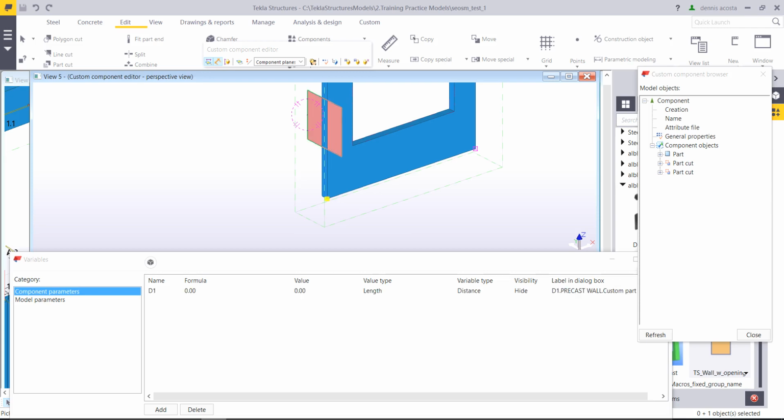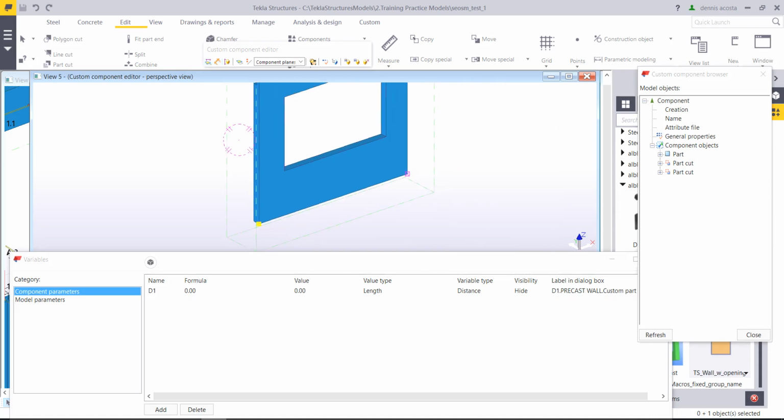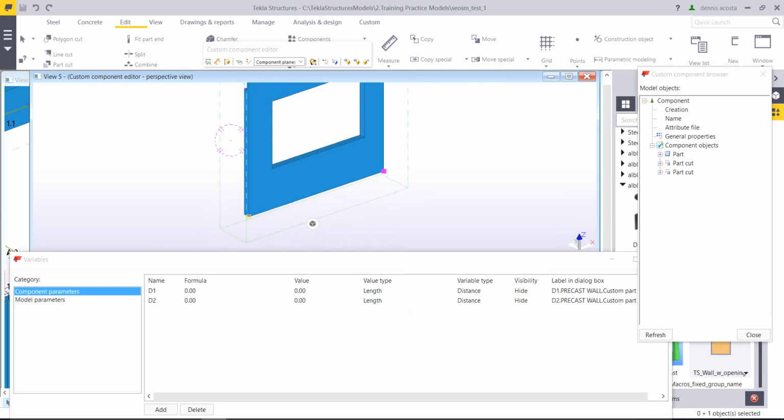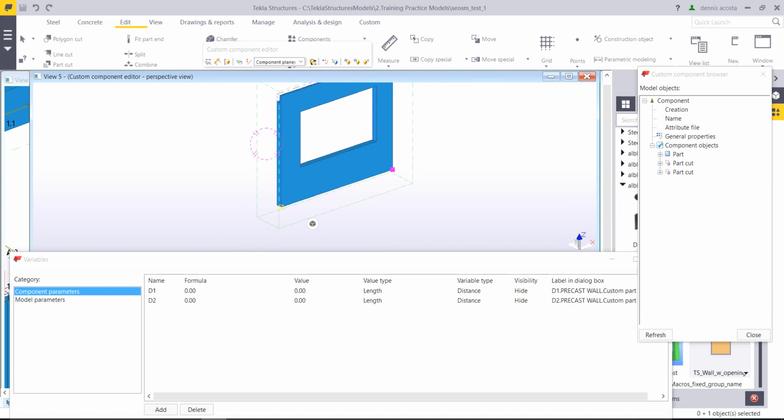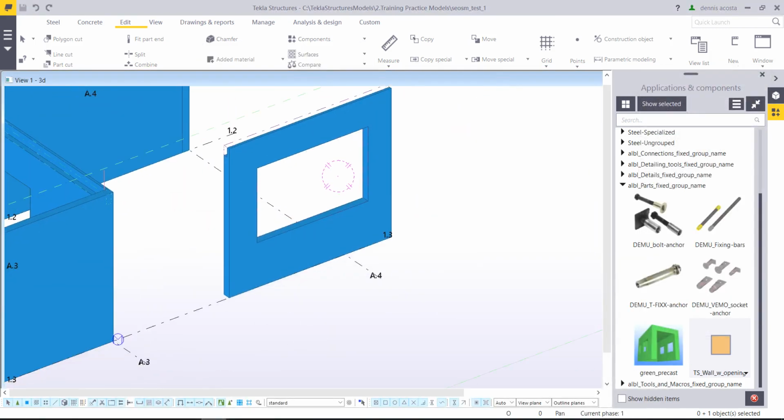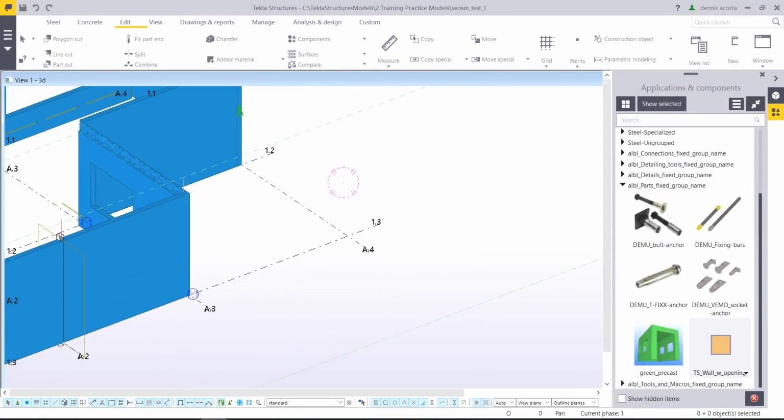So if I click this one, the value will be 0. So it means if I pick this point, the wall is always 0 at this point, unless I put a value here, unless I put an equation here. Okay, but leave it there, 0. Then next, right click, interrupt, select the endpoint, bind to plane here. Okay, so I have 2 pick points. So what will happen if I close this one and then save? Say yes. Look, here if I click now 1 and then 2, this is my wall.